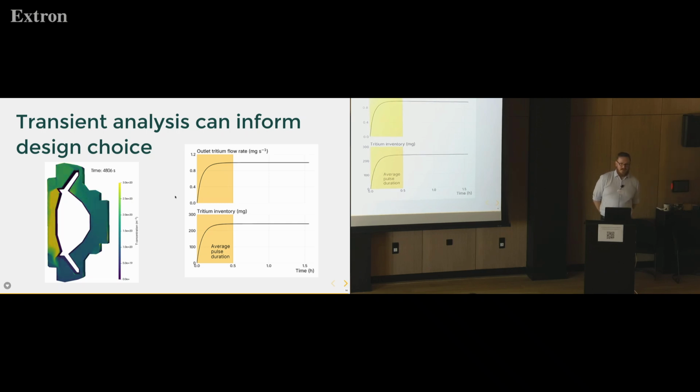Absolutely. I think there's a lot to be said for doing CFD in FEniCS, because we have been having a lot of issues. As soon as you try to interpolate results from OpenFOAM into any kind of mesh in FEniCS, you lose some data that way. Actually, the issues we were having initially were that we were naively interpolating it into a CG space, which lost all the divergence-free nature of the solution you get from OpenFOAM. So that's something we've been dealing with.